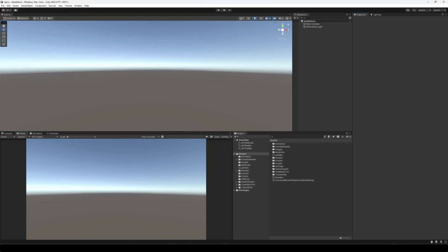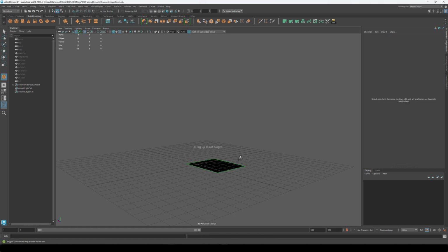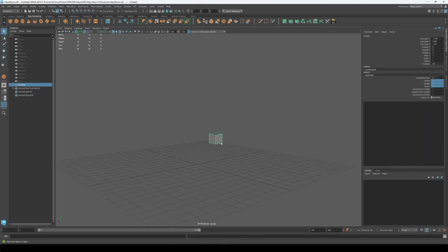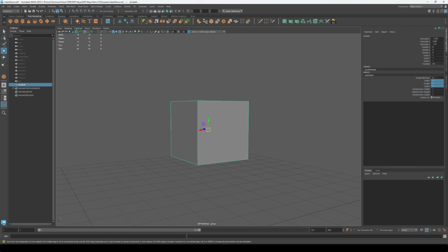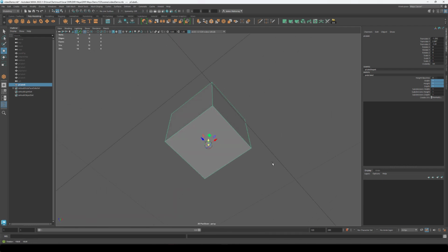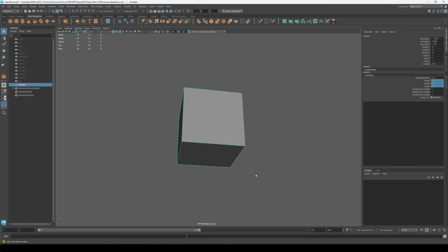Let's set that up. In Maya, create a cube, 1 Maya unit by 1 Maya unit. Snap the pivot point to the center bottom face and set that to the origin. Hit D to move the pivot point, W for the move tool, and hold V to snap to the vertex. If you select the Y-axis and middle mouse click to snap the pivot to the bottom of the quad, it won't go to one of the vertices. It'll just go right to that level. Hit Q to get out of pivot mode.